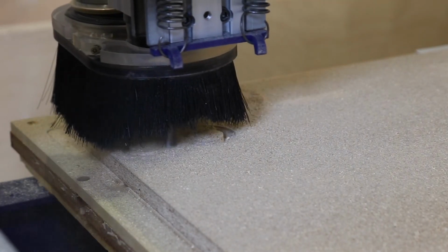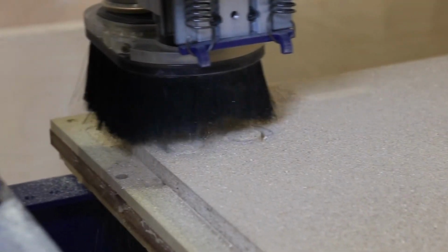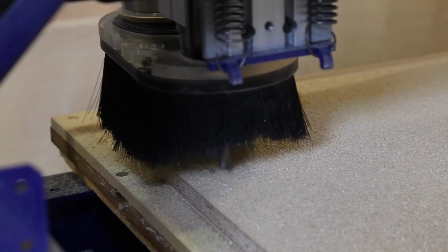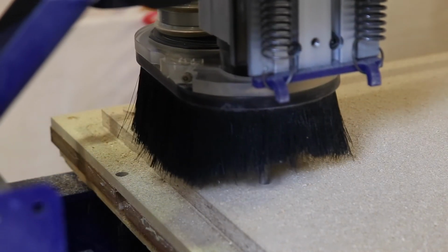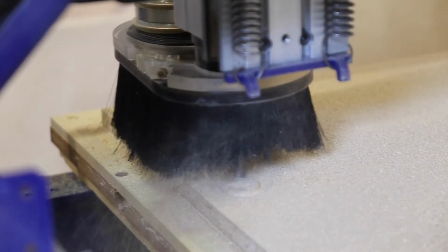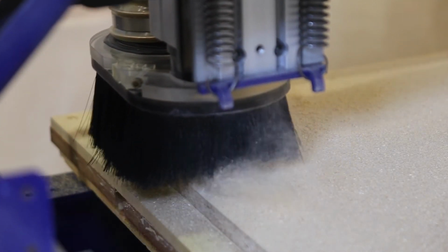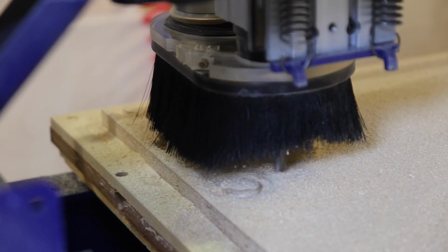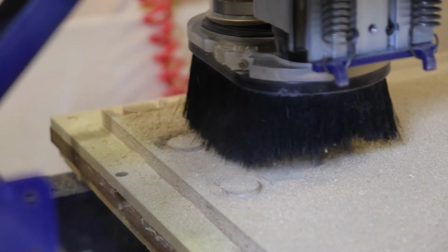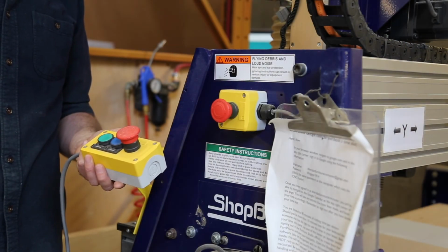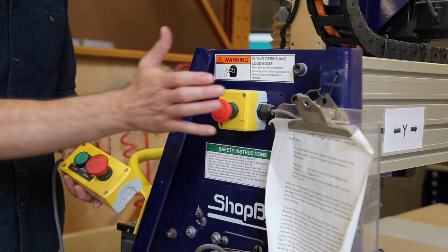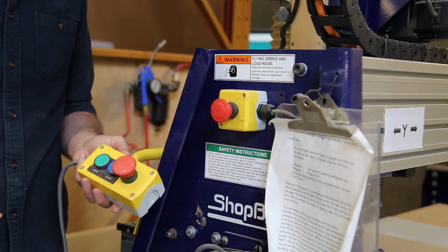When your cutting file is running, the best approach is to carry the wireless keyboard as you monitor the machine. Touch the keyboard space bar or left-click on the mouse to pause the file, which you may resume or abort by following the screen prompts. Do this if you need to pause the file temporarily to check the cut depth or use the washroom. In an absolute emergency, hitting the red emergency stop buttons on the yellow remote switch or the end of the gantry will stop the file and all motors immediately.